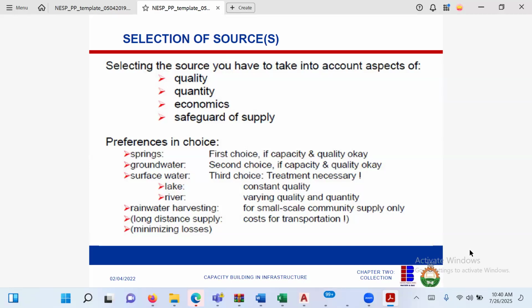That's why in big cities, they will put a buffer around their water source. Sometimes it can be 1 kilometer radius. Nobody does farming, even farming. Because when you allow farmers to be around the water source, those of them who are using NPK fertilizers, you begin to see a lot of nitrogenation of your water. And you know what nitrogenation of water means? It means growth of algae, and some of these algae can be very dangerous to the body.